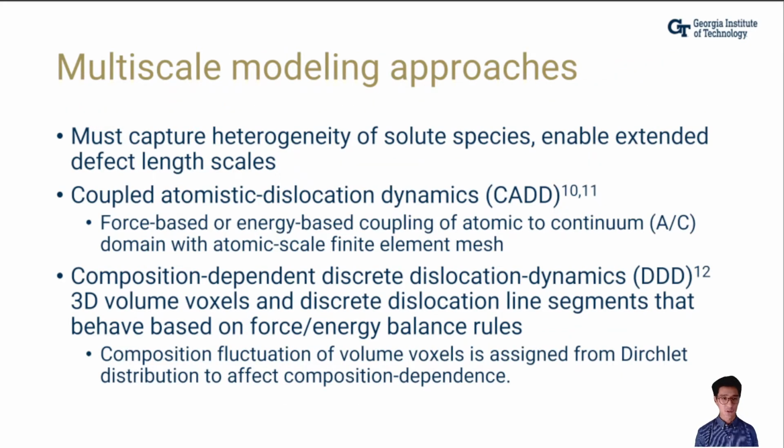Multi-scale modeling approaches must satisfy the requirement of solute composition fluctuation dependence and access the extended length scales required for converged calculations. Coupled atomistic dislocation dynamics approaches, CAD, use force or energy-based coupling to bridge fully atomistic domains to continuum domains. Also, recent composition-dependent discrete dislocation dynamics simulations describe discrete dislocation line segments and represent solute concentration dependence by randomly sampling the composition of regions in different voxelized volumes.